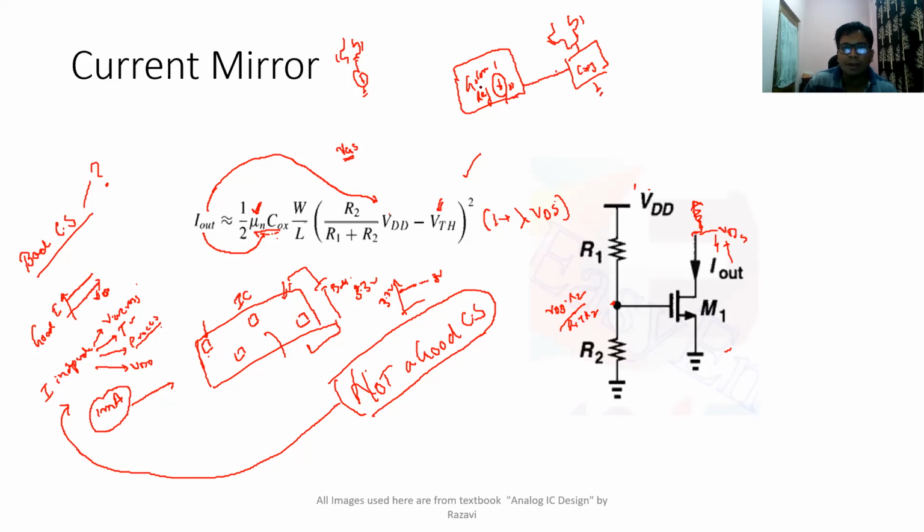In the other circuit, let us say the common source amplifier with current source load we just saw, instead of placing a current source there, we will use a copy circuit. We will simply copy the ideal current from here to here and then use it.